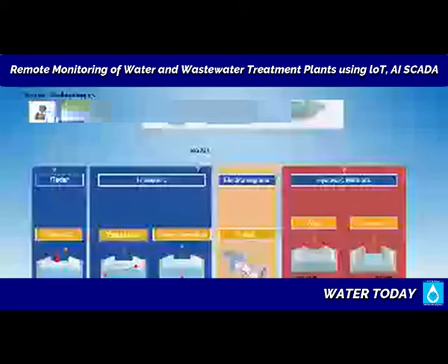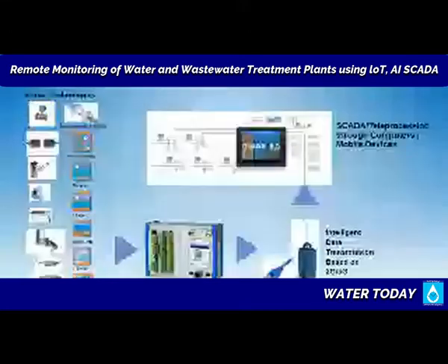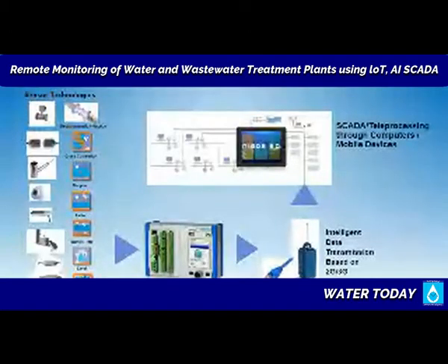You have the technology that is suitable for open rivers, which are wide, very wide rivers, like the sensor that's there that normally carries a 500 kilohertz crystal sensor, low frequency crystal. Otherwise, typically these open channel meters go up to a 1 megahertz crystal sensor, and in the gigahertz range if you are using radar for surface measurement.